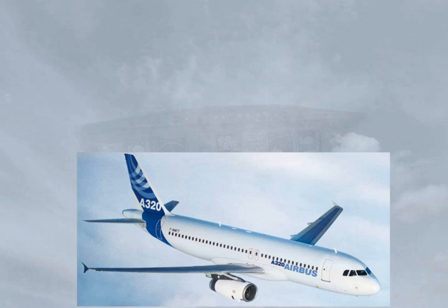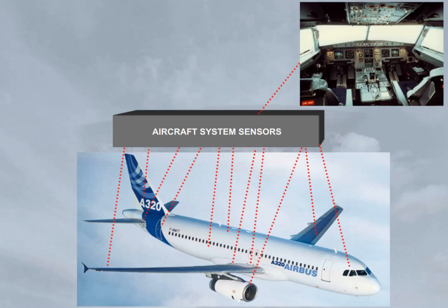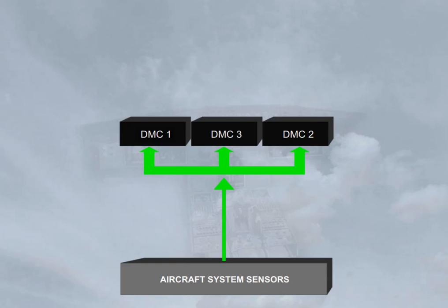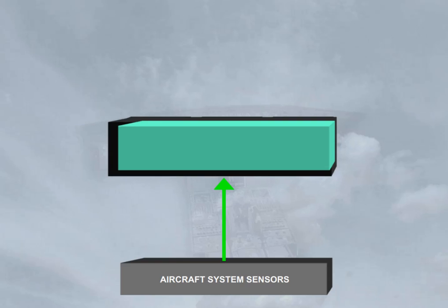Sensors are installed throughout the aircraft to monitor the various systems, including system controls, operated on the flight deck. Some parameters, for example fuel quantity, are routed directly from the system's sensors to the 3 DMCs. Note: each DMC has one channel, which can provide simultaneously the management of the EIS and the ECAM displays.